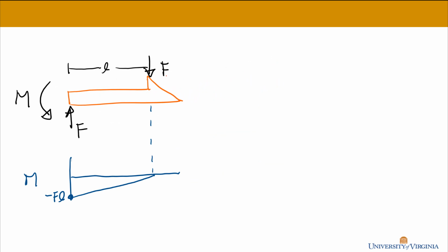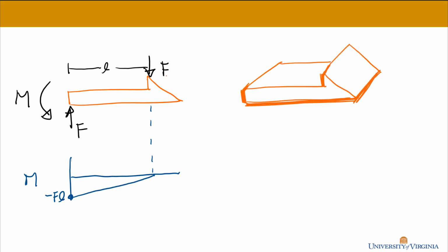So maintaining that thought, let's see what this looks like in 3 dimensions. Your snap fit looks kind of like that, right? Well, you actually don't need that much material at the tip as you do at the base in order to prevent failure. We talked about stress being the thing that causes failure, and stress is a force per area of the cross section.